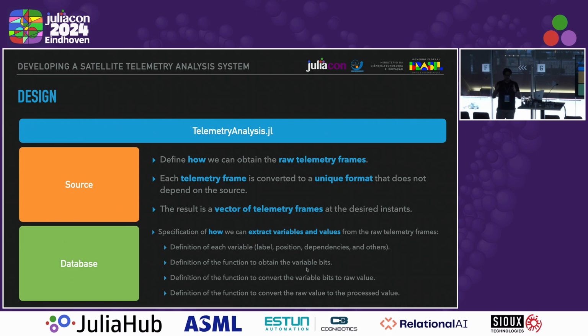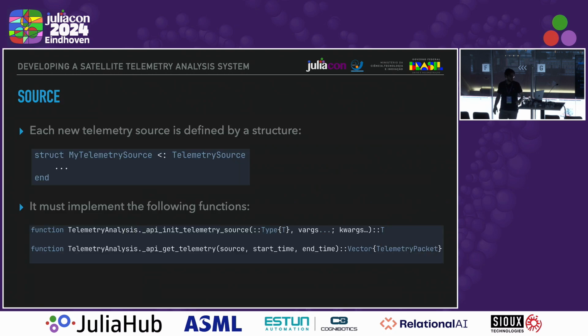And then how you can obtain the bits, because things can get very messy. For example, you want to pack everything, and normally the information is not byte aligned. For example, you sample an AD with 12 bits. So it's not byte aligned. It's just this part of these 2 bytes that has meaningful information. Everything you have to code here in what we call the database.